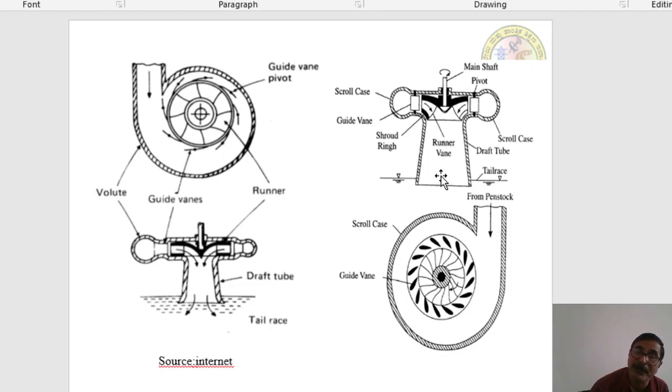That's why a conical tube or conical pipe is attached, which converts the water pressure which is below the atmospheric pressure into high pressure because the area of the conical tube gradually increases. As area increases, velocity decreases and pressure increases, in such a way that it should be greater than the atmospheric pressure.